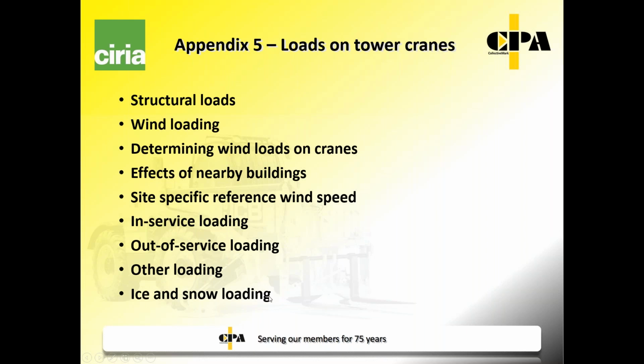Ice and snow loading is not normally considered by tower crane manufacturers unless the crane is going to be used in alpine regions, and in that case the purchaser generally asks for specific information. So in the UK we don't normally take account of that.